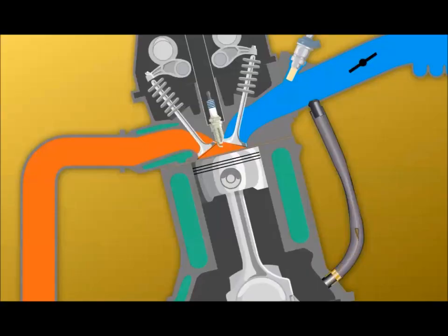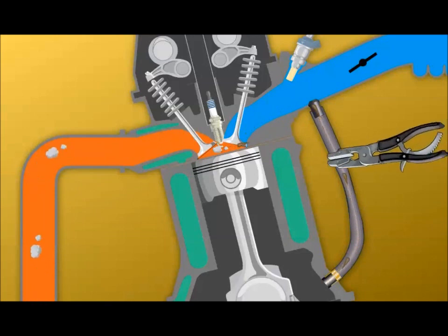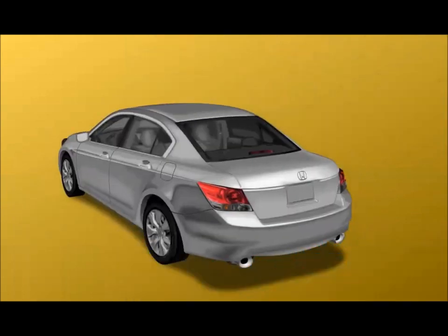Also check the PCV system for faults. If the crankcase is not correctly vented, the PCV system can feed oil into the combustion chamber. To check for this fault, clamp the PCV hose or block the PCV system. With the system blocked, check for smoke while driving. If the oil smoke clears up, check the PCV valve and crankcase venting system.